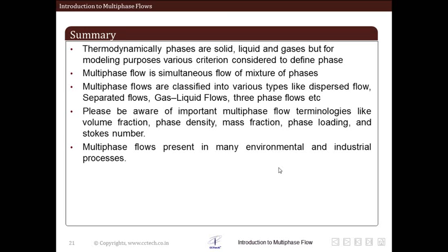So don't have a perspective of just a thermodynamic phase, like the three phases of solid, liquid, gas, but learn to treat the entire flow as an entity, and then classify whether the flow is multiphase or single phase. Multiphase flow is the simultaneous flow of a mixture of phases, and it is classified into different categories like separated flow, gas-liquid flow, three-phase flow, etc.